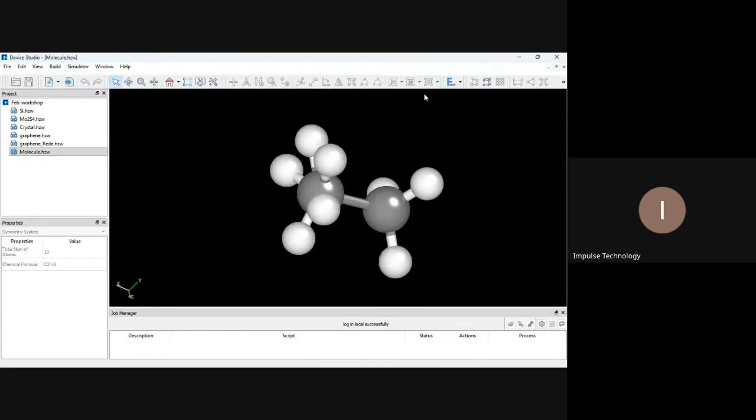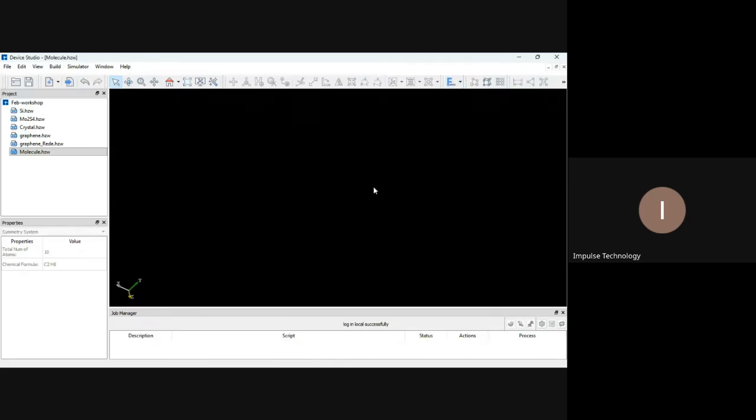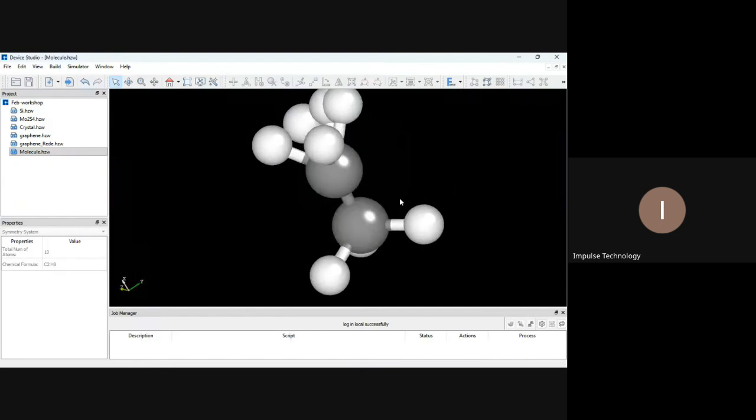At the top section, you can see force field calculation. It basically minimizes your structure, like the molecule structure. Choose according to your molecular structure and choose any algorithm like GFF. According to your material file, you can choose the algorithm to minimize the structure. It will take some time to minimize. You can see it minimized the structure.